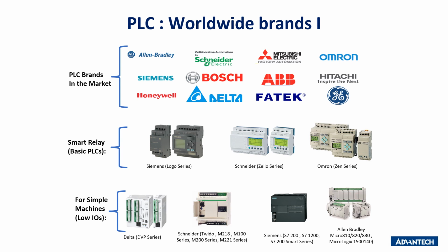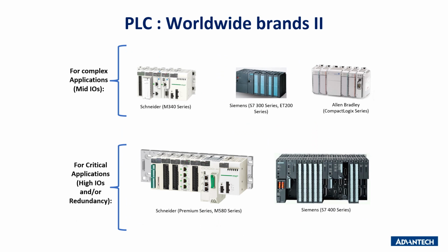According to the application, we can find PLCs dedicated for basic applications with smart relays such as Siemens Logo Series, Schneider's Zelio Series, and Omron Zen Series. For simple machine applications, we can find Delta DVP Series, Schneider Twido Series, Siemens S7 Series, and Allen-Bradley MicroLogix. On the other hand, for more complex applications with a middle number of inputs and outputs, we can find controllers such as Schneider M340 Series, Siemens S7 Series, and Allen-Bradley CompactLogix Series. Finally, for critical applications that require a high number of inputs and outputs and redundancy, we can find Schneider Premium Series and Siemens S7 400 Series.